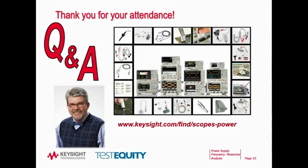Okay. Can the scope's control loop response measurement be used to perform other Bode plot gain and phase measurements, such as characterizing amplifiers and filters? Oh, absolutely. In fact, I think the measurement results would probably be a lot better because you wouldn't be in an environment with lots of switching noise. If you're just measuring a passive filter or an active amplifier, this particular tool is going to work very well. Still probably not as good as a standalone network analyzer, but it's going to do very good.